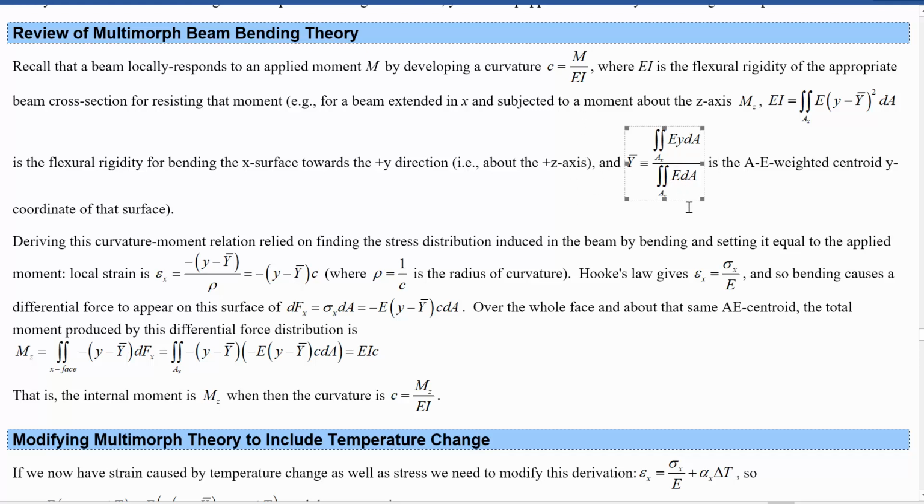If you're talking about an asymmetric material too, like an anisotropic material, then the E that we should use in this equation is the effective E in the longitudinal direction. That's the E that's going to matter for resistance to bending here. Not the E that's in the Z direction, but the E that's in the X direction in this case.